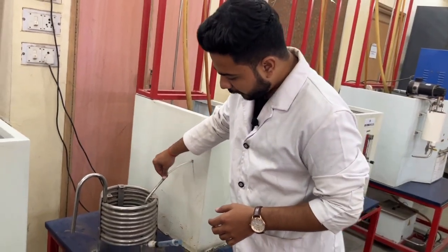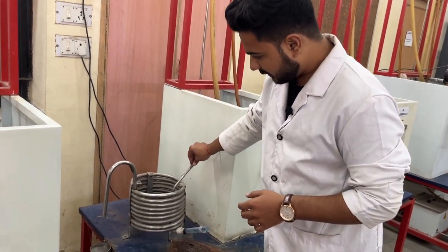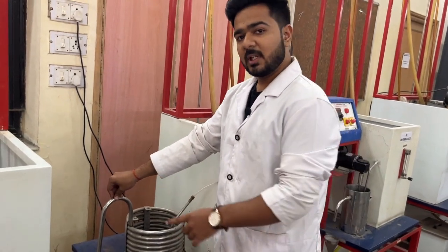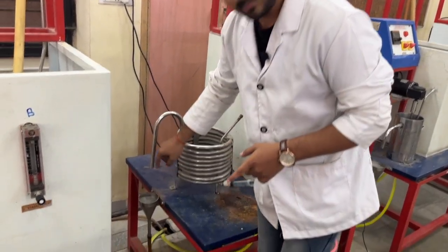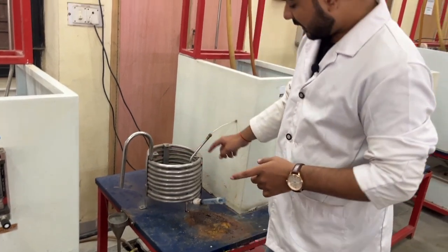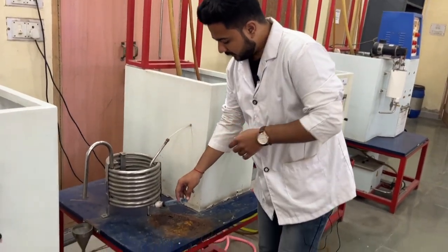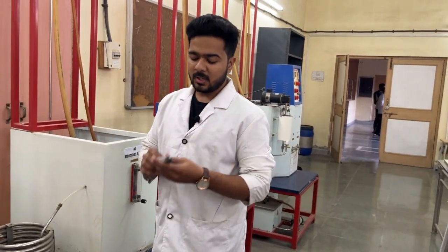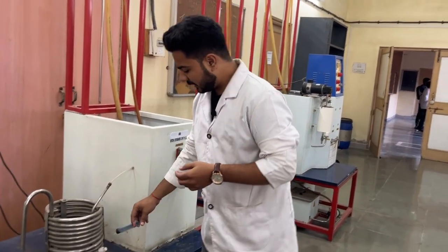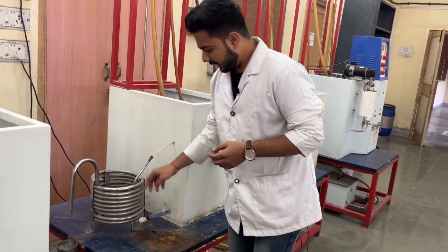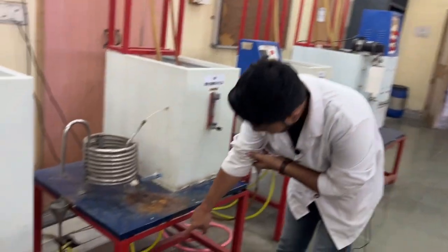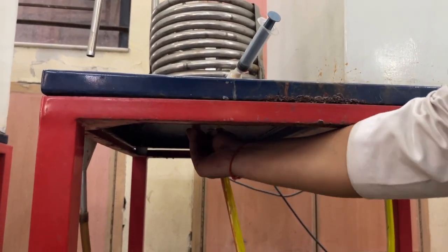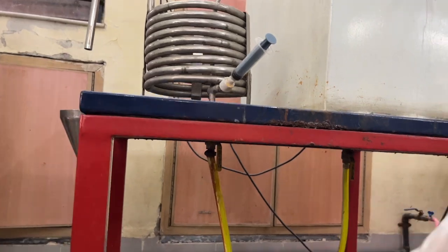We have a long coil PFR which has an inlet through which the liquid is supplied and an outlet through which the liquid flows out, and the sample knob through which we take our samples. This has a tracer inlet through which we give our input. In this experiment we are going to give a step input, so we will be using a syringe through which we will give a step input. And further we have a drain knob down there which is used to drain the experiment after the experiment is complete.